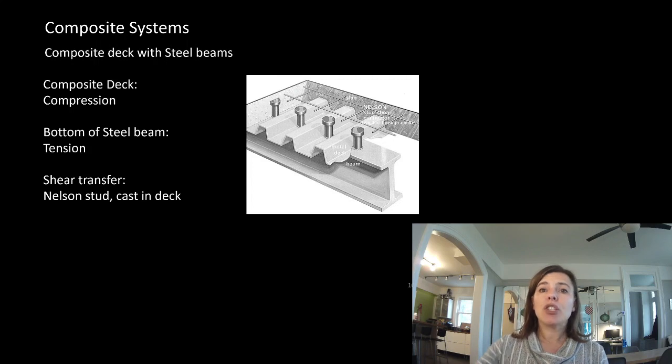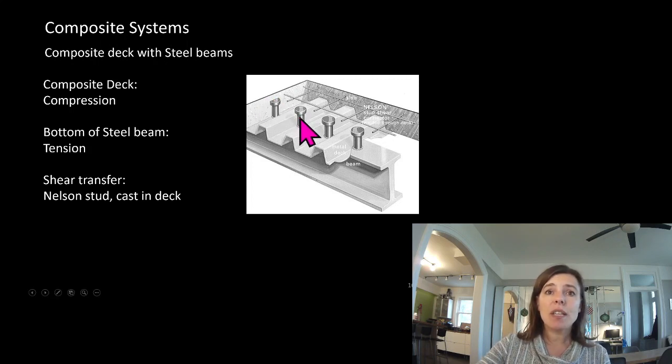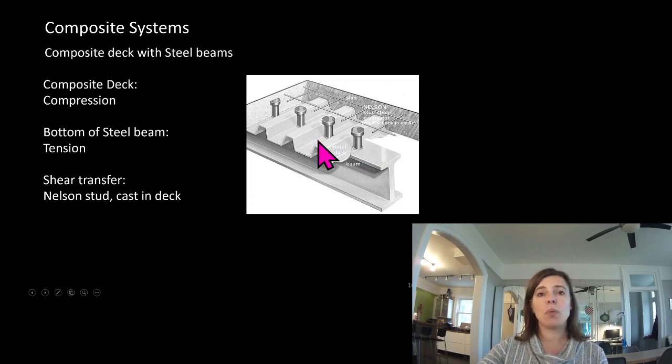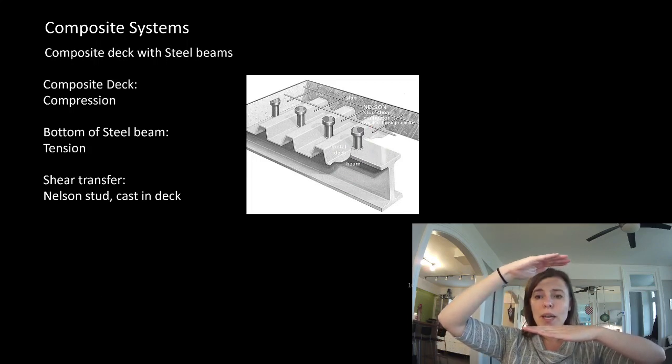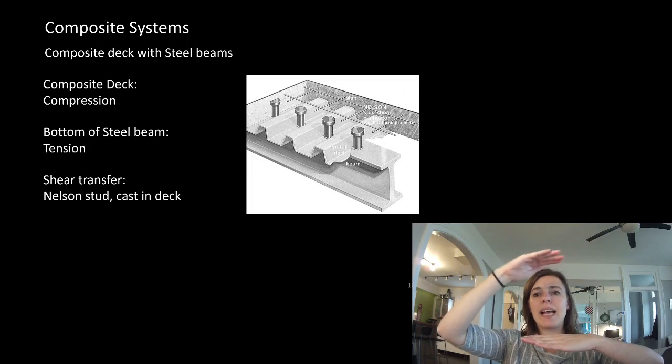If we punch steel studs down into our steel beam, and I talked about this when we looked at steel systems, you can actually make use of a little bit of the concrete on metal deck as the top of the beam. So instead of a beam just being this deep, we get to use a little bit of the deck and concrete as well.